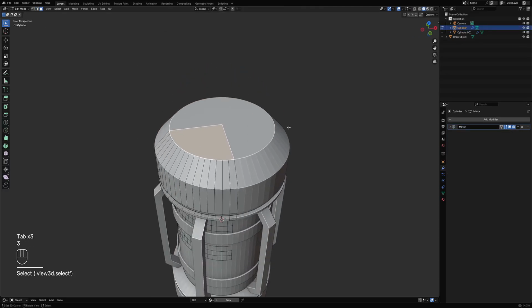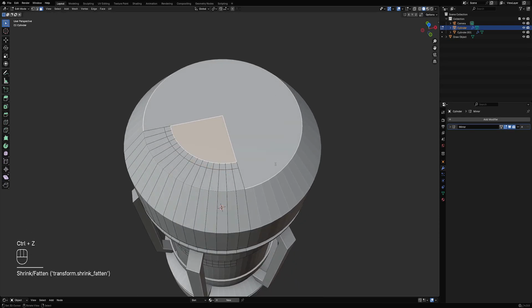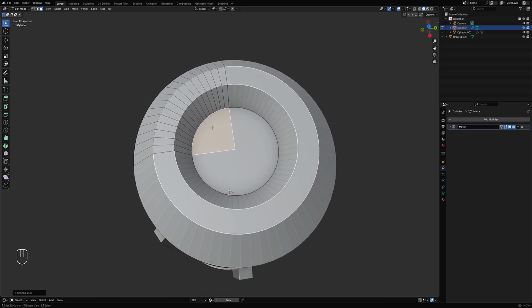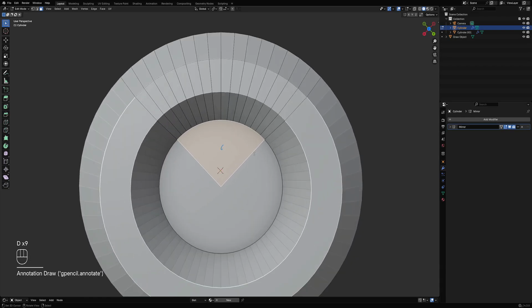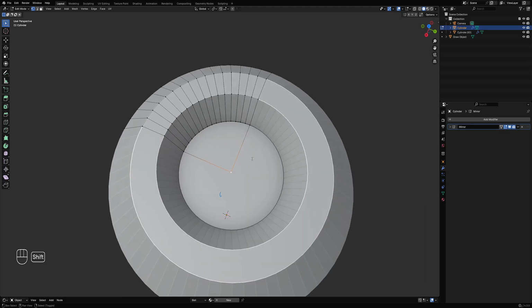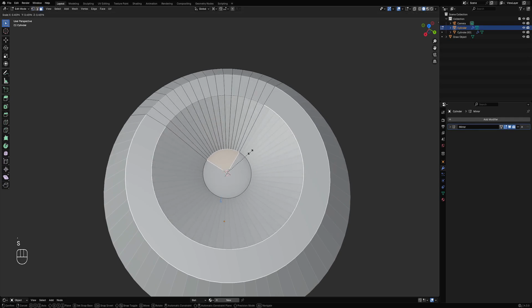And then our base mesh top and bottom side. So instead of scaling, I'm undoing, because you can't really correctly scale if you have the mirror modifier, because the median pivot point is right here. So if you scale this, it's going to do that. So you need to pick a center line and cursor to selected. Set the pivot point to the 3D cursor, and then you can do that.